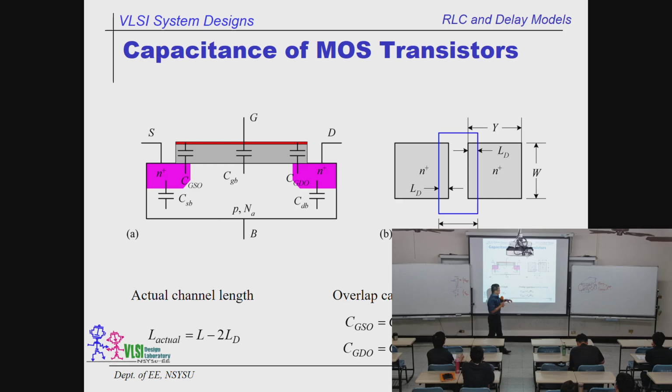And check this purple area. This area is meant to be the source or the drain, and they are made of diffusion. But remember one thing: even though we use ion implantation to create these two areas, unfortunately, these guys don't follow the rule. Some of the extra material will be diffused under the gate.